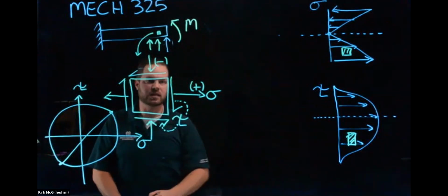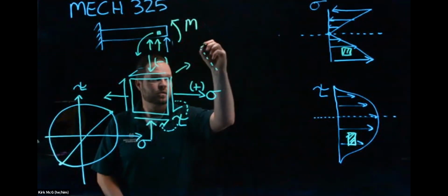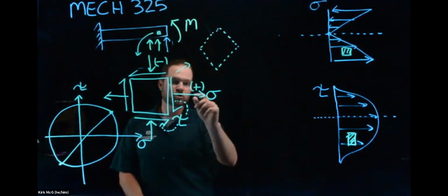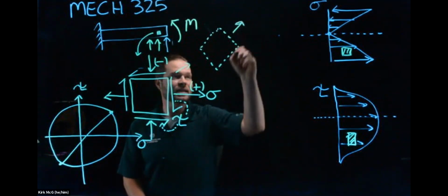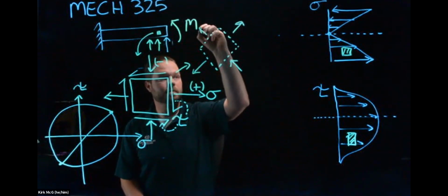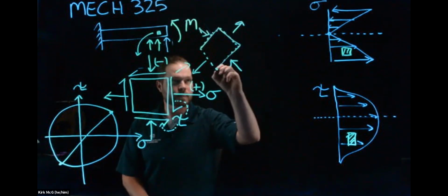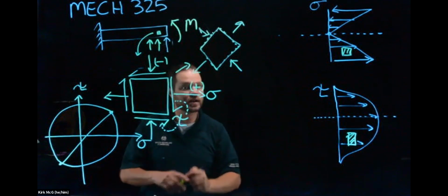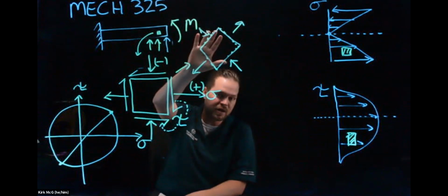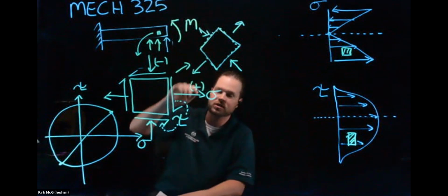However, I can rotate this element, meaning I can go from here to, say, it's a pretty poor square, but I can rotate that such that I've simplified it so that I only have normal forces on it. Whoop, like that, okay? So by rotating it, I haven't changed the loads or anything like that. I have just simplified the stresses on the component to make further analysis easier. So this is a tool we teach you in this class, how to do this rotation.